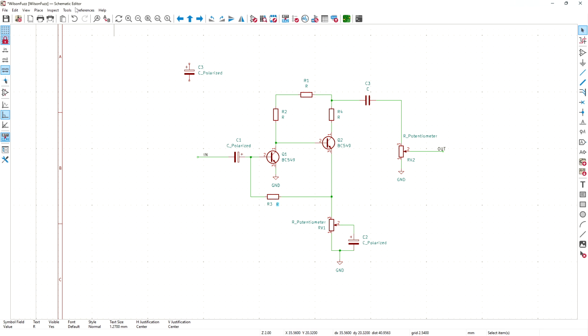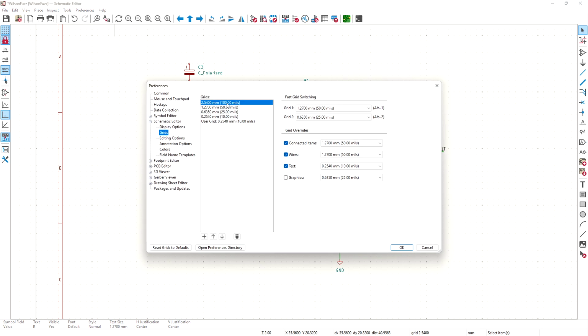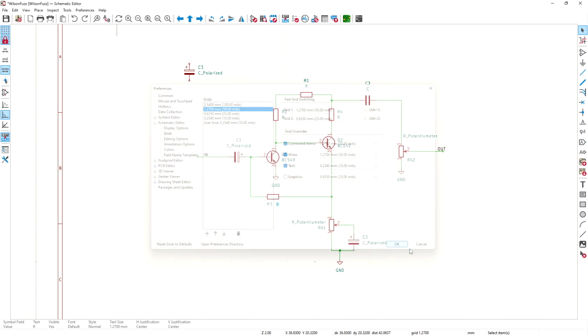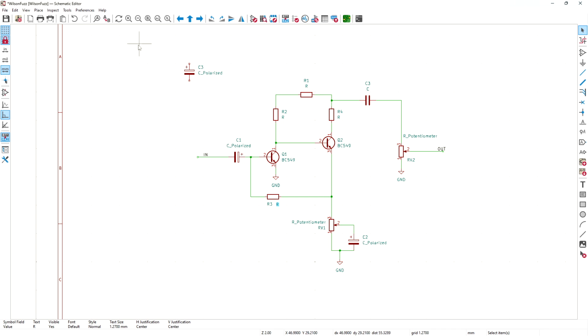Oh, actually, this is a new thing. So this text is aligned at 10 mils, but wires are aligned to the grid. Maybe you can see the grid here, but anyway, when you're moving your components, you see how it steps to the next grid point. It's not smooth. It's just easier to draw. But text is not aligned. It's 10 mils, so on my trackpad it's a bit tricky. Okay, I talk too much, so I'll try to speed this up.